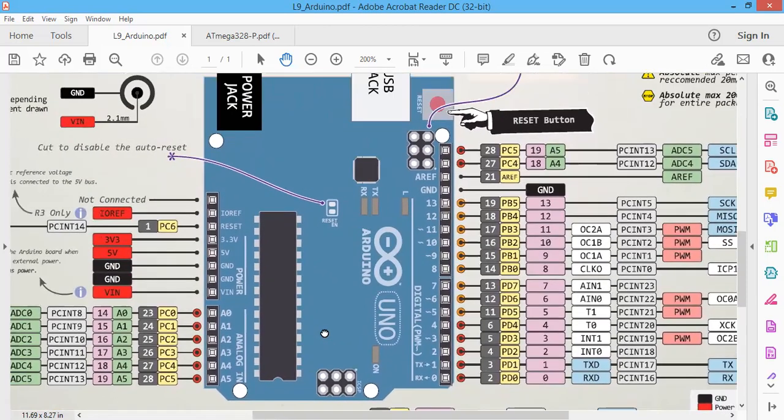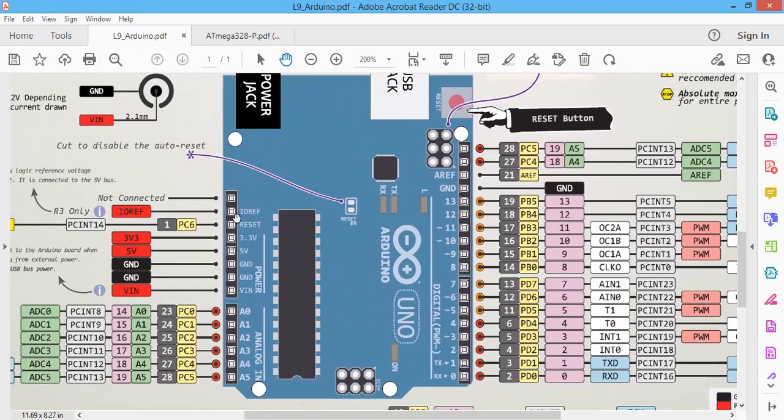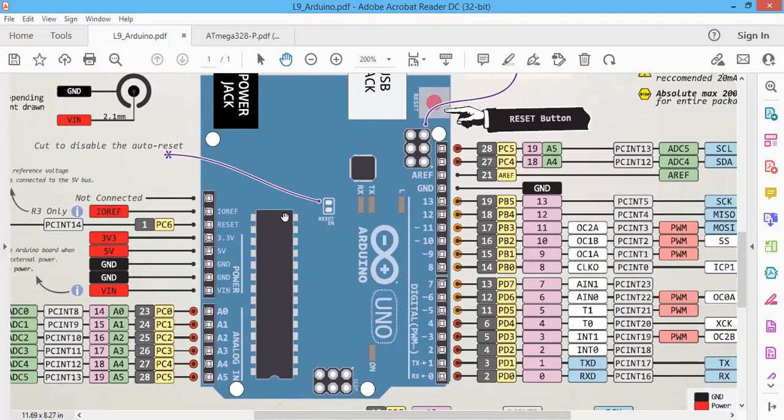That can happen for different reasons, like a bad program, or some kind of EMI interference with your chip, or any kind of voltage spikes coming from this Vin or these external supplies, or voltage spikes coming from your analog signals, digital inputs, or any communication channel. That will get your code stuck, so then you can reset and get the system working again.